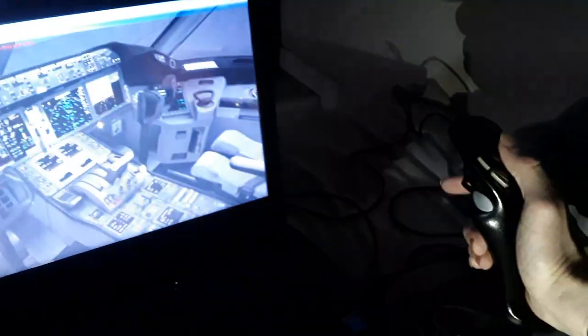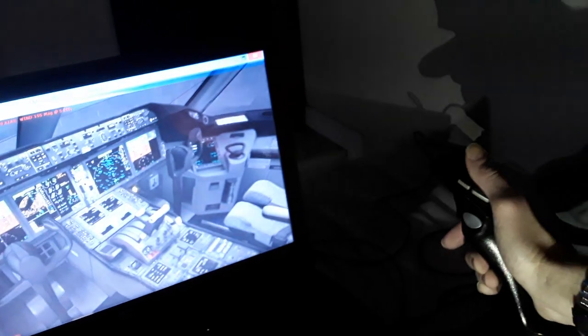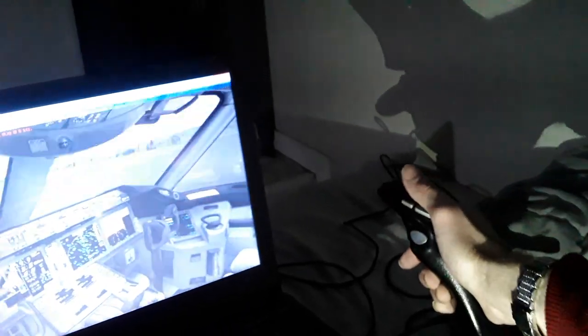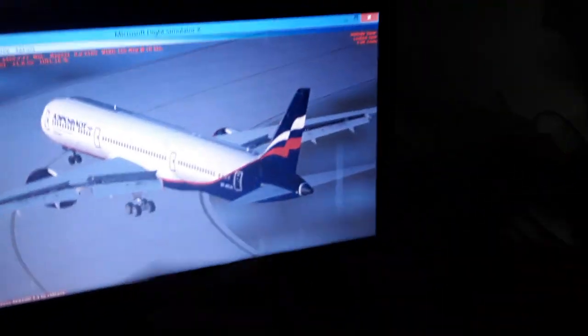So the flight control computers take the input, the command from the side stick of the Airbus or the yoke of the Boeing, and they adjust the flight controls in flight in terms of acceleration of the gravity and rate of turns or climb. So it's very easy to understand. So it's not full flight controls deflection at flight conditions at normal flight controls.